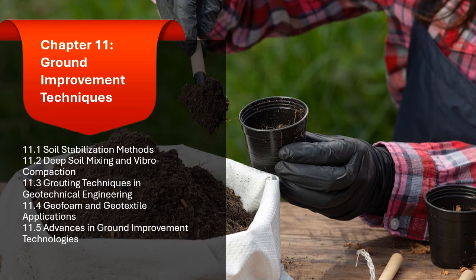11.3.1.2 Compaction grouting. Compaction grouting involves injecting a thick grout mixture into the ground to displace and compact the surrounding soil, thereby increasing its density and improving its load bearing capacity. The grout is injected under pressure, causing the soil particles to shift and compact as the grout displaces the soil.